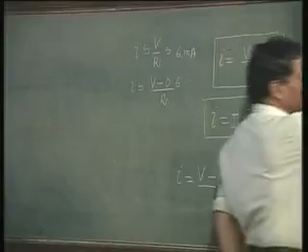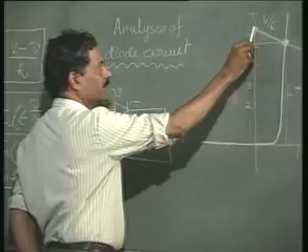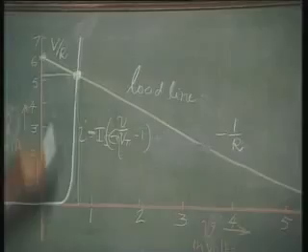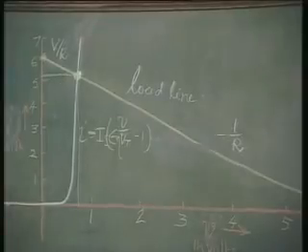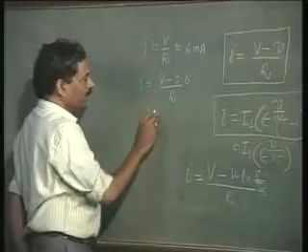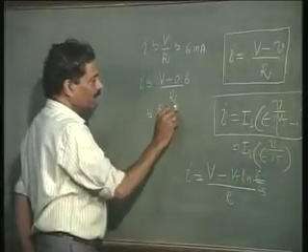It is not so. It is less than 6 milliamperes. 6 milliamperes is this, assuming that the diode drop is 0. So, this value we would have got of current if we had gone for the second approximation, which is V is equal to 6 volts minus 0.6.